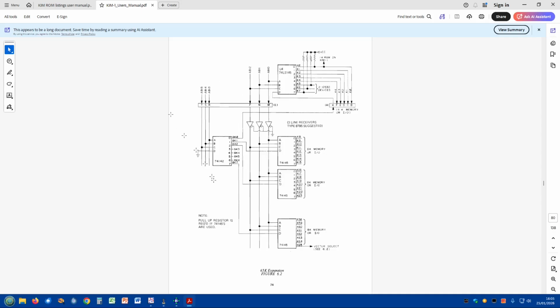So I'll be using a similar system to this to decode the extra boards that I'm going to plug in. I won't be doing a full decode, but I'll be doing some to make sure this doesn't come on. And I'll be doing some in-between bits, trying to put some RAM in, but not the ROM or vice versa, to try and test different parts of the other actual board, to check that the RAM's working, and see what we can fix about this ROM.